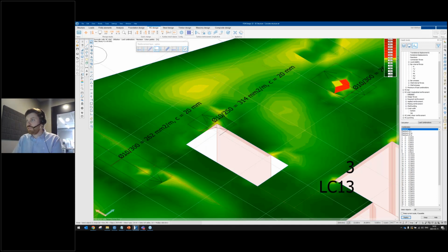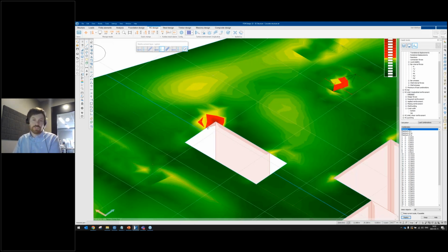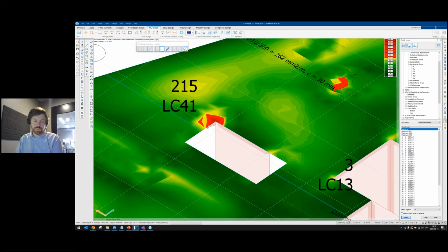So let's remove these actually, both in the top X and top Y direction. And you will see now some overutilization at this edge. And as you can see, the result is automatically updated when I make changes, and you have a setting here that's auto update RC shell results if they already exist. I can turn this on and off here, but I want to keep it. It's easier, in my opinion, to work with the software when doing manual design, when you get an instant feedback and an instant result from the software. So let's go into the manual design.